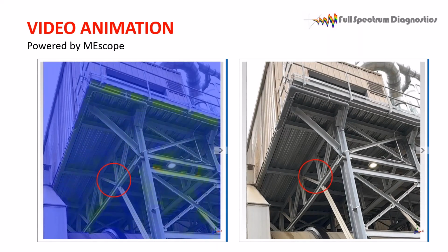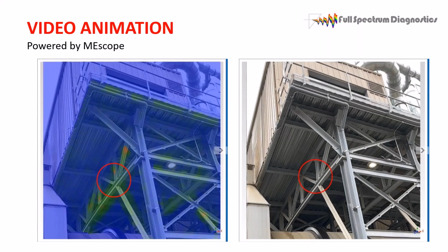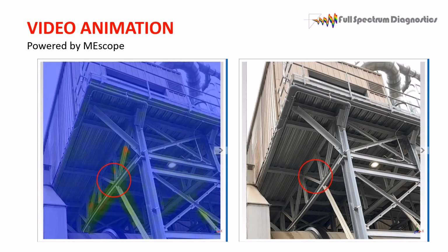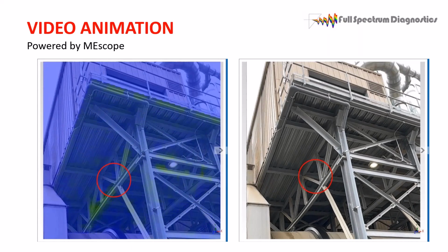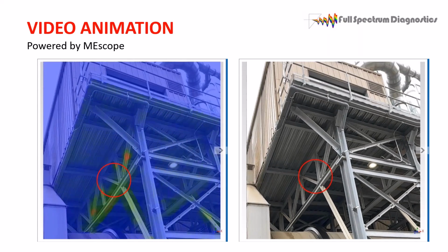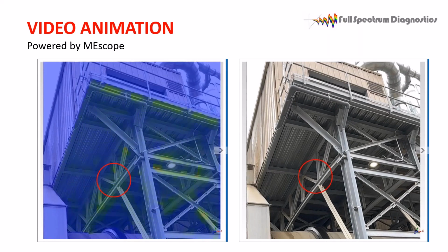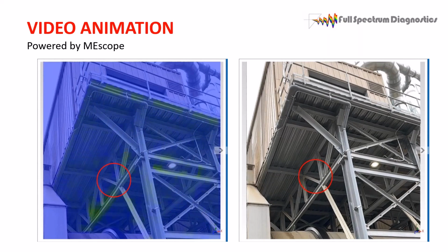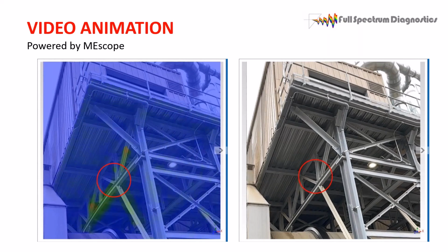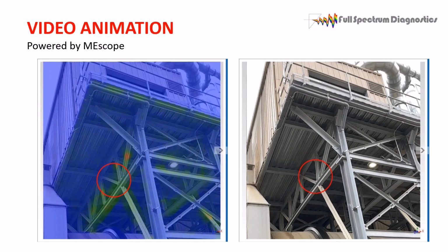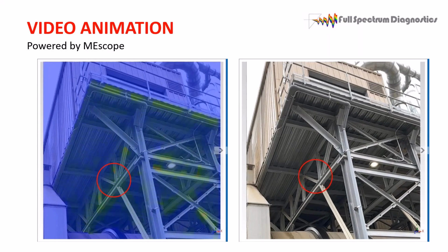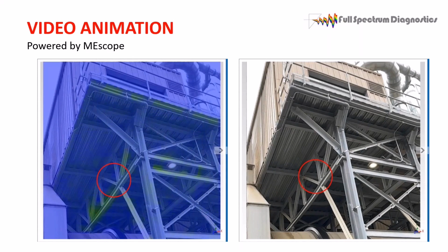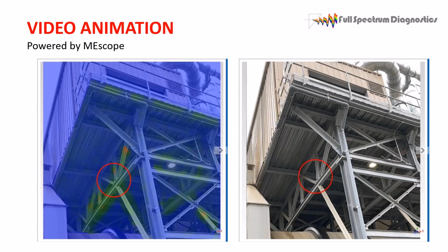It's very interesting. The sifter is on that deck above it, which is, I don't know, a 6-inch slab of concrete, with a machine that's sitting on top of it, and it's eccentric, and it throws the beans and shakes them and does all kinds of stuff to them to try to break up those shells. And unfortunately, that spinning frequency was the same natural frequency as the truss underneath.